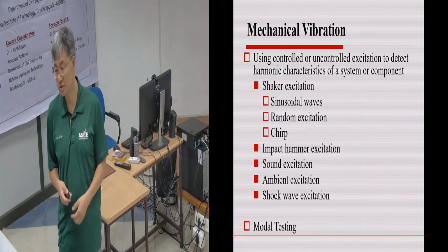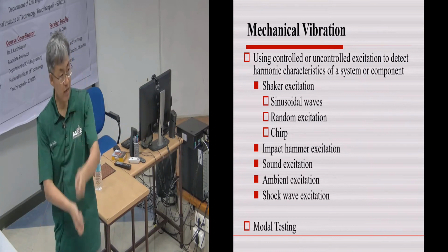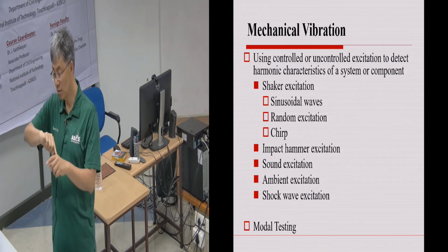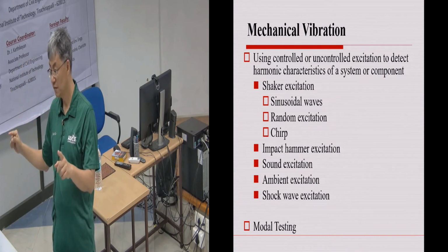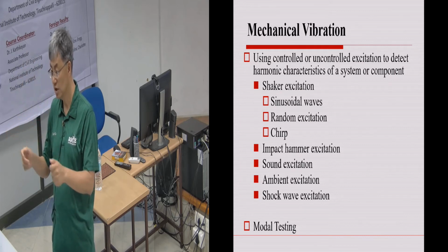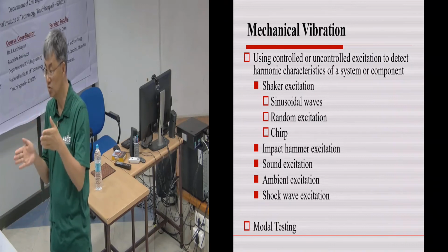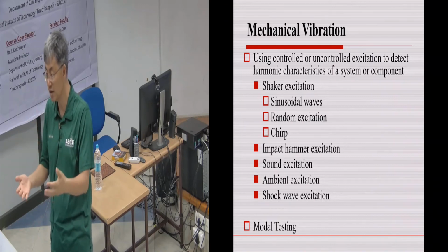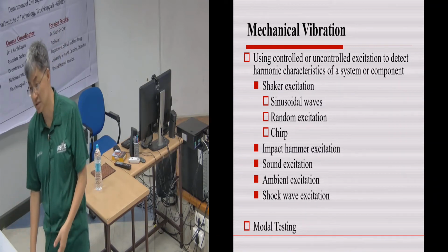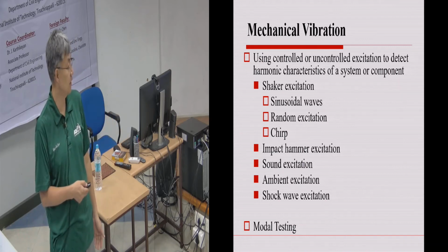And the hammer is usually the more preferred technique, because when you use a hammer to impact, you are generating a broadband wave, and that broadband wave usually has many frequency components. So when you hit the ground, one hit causes many modes to happen. That's the preferred method. But again, you have to be trained in doing that kind of testing. So all those are required techniques.